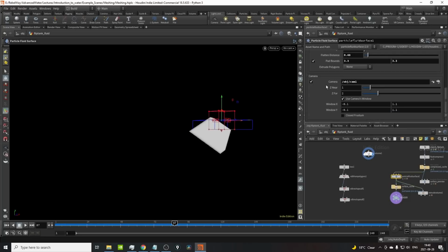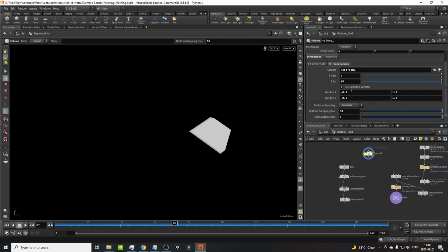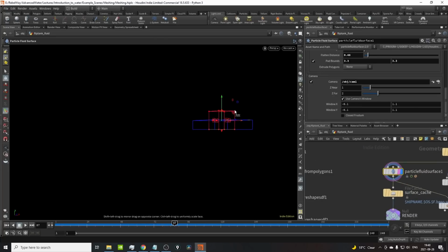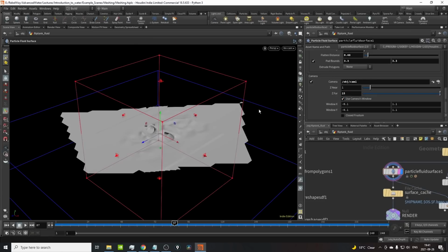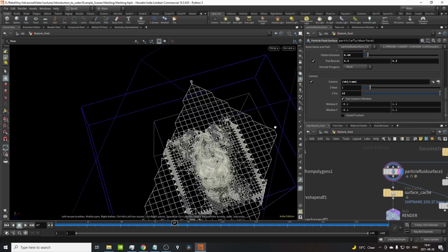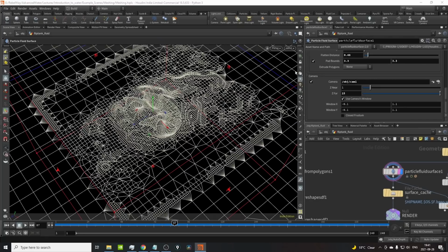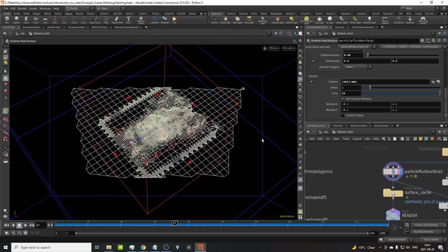And that's exactly what this option does, right? All of these settings now, they're here. The only thing is you don't have a resolution setting, because that's picked up directly from the resolution settings earlier. And if we look at this and we give it 15 meters, then boom, we now have a water mesh that is perfectly viewable from our camera, and we don't cache more surface than what we need. Now this is great, right? This is fantastic.